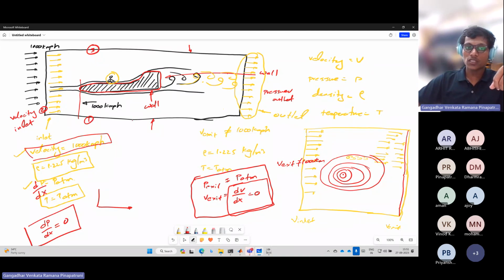That means though I selected edges 1, 2, 3, I give a boundary condition such that only velocity in the x direction equals some finite value, but velocity in the y direction equals 0. That means even with a velocity boundary condition at this point, you will have only x velocity along this, but there won't be any vy velocity in the upward direction.